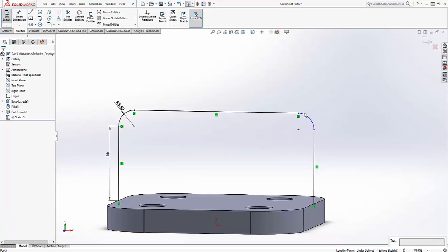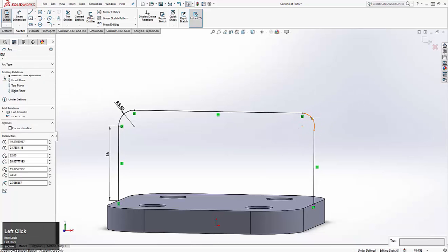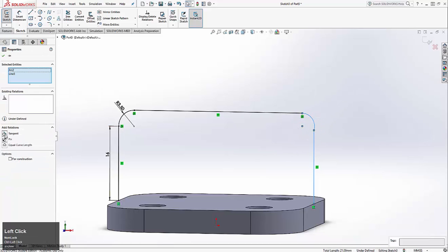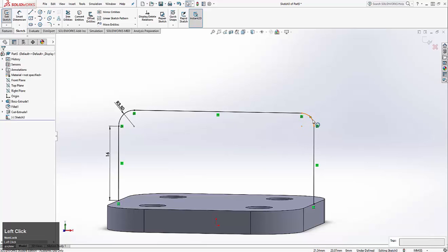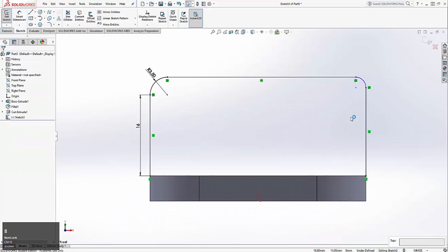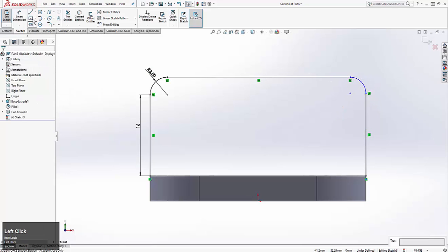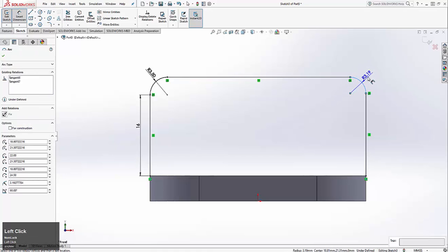This arc right here, it's blue now. Why are you blue? Okay, so I think it's because this is not tangent here either, so we can do that. Oh, and this is, okay, goodness. So I'm going to do Control 8 again. Once again, this arc doesn't have a size. Like before, you could say smart dimension this and call it 3.5.